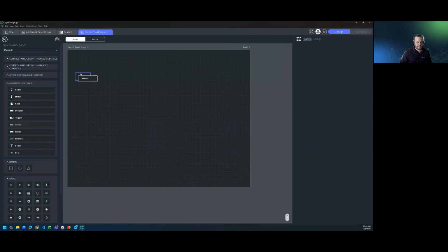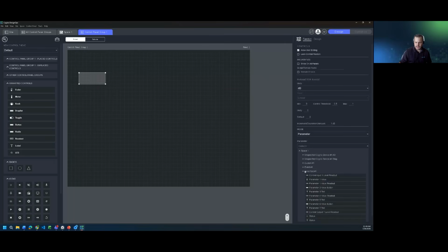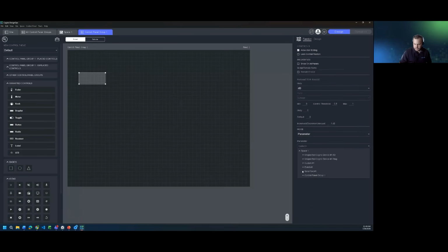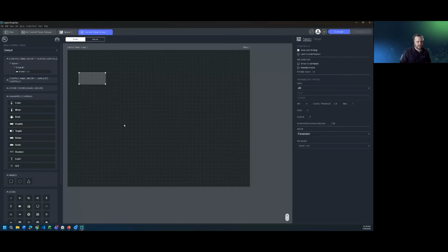So again, if I set up whatever button I have on my screen, I can choose parameter and just tie that to that TCP send that I have. Right, and then that will send the string out to the other device. Receive string as well. Yes, you can set up receive strings, and we have Lua as well as our custom programming language that you can basically set up any third-party control with, either sending out or receiving from others.